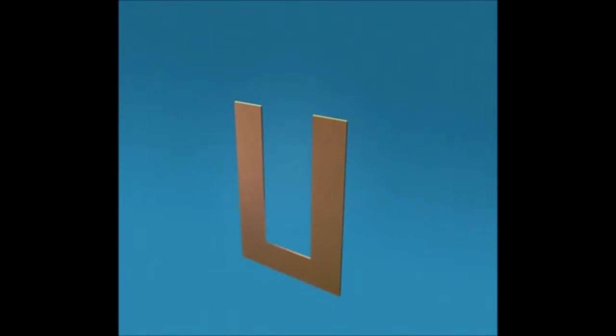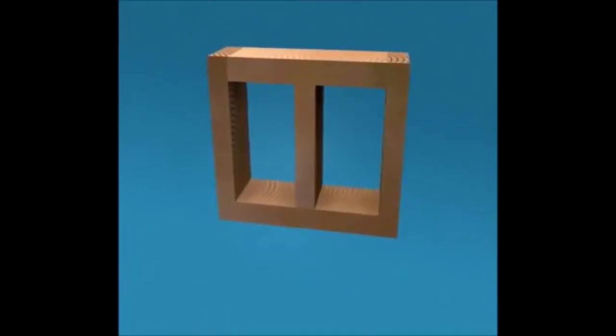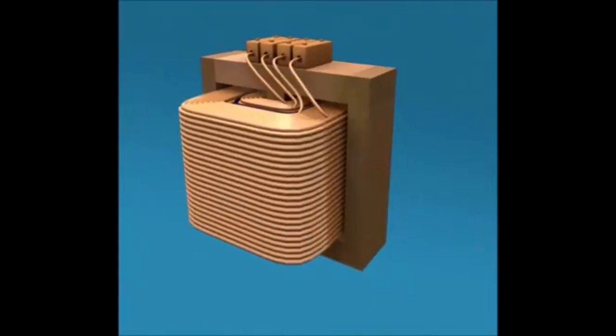The problem with the construction discussed so far is that the two windings are well separated from each other, and there is considerable reduction of magnetic coupling and hence of the efficiency of the transformer. This disadvantage can be overcome by constructing the core like this, in which the two windings are brought close to each other, thereby improving magnetic coupling between them.